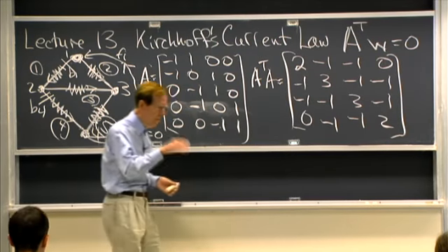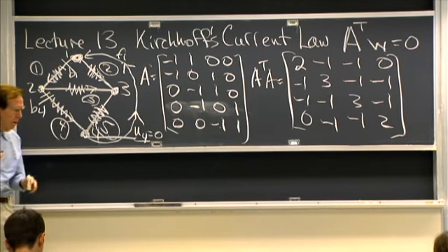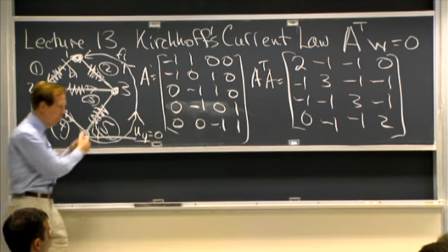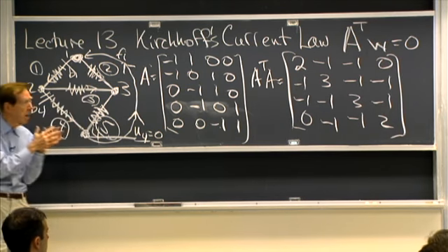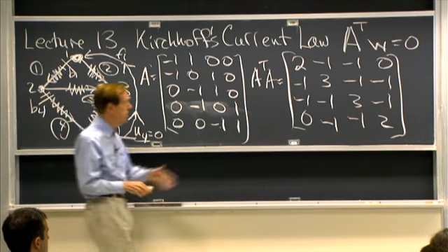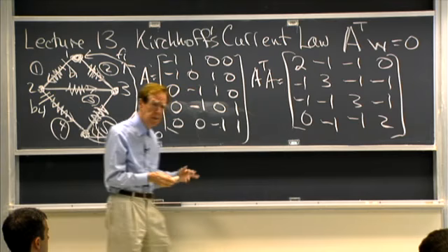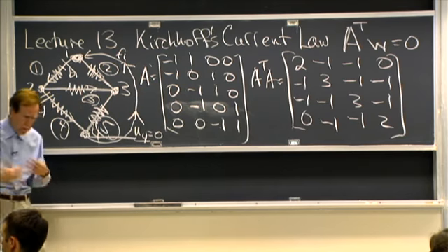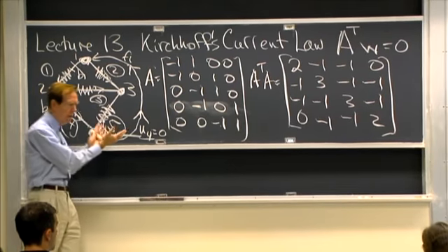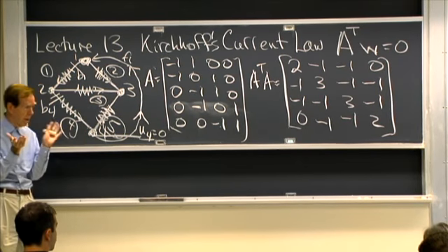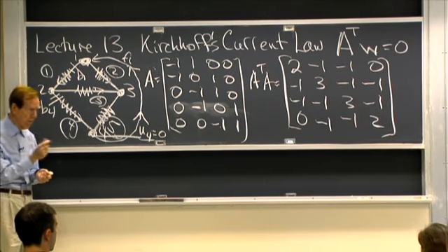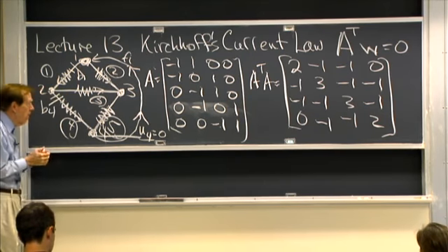And looking ahead, just a small comment, this will have exactly the same thing in so many other applications. In big finite element codes, you produce a stiffness matrix that's initially singular, and then you impose the boundary conditions. That's the efficient way to do it, is create the matrix first. That's the big job. Then impose the boundary conditions. That's the small but occasionally tricky part.